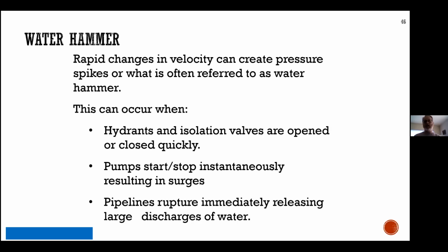And if you've seen pressure gauge readings on a system where someone has shut a valve closed, it can be up to 200% of the operating pressure in the system. Well, that will damage pipeline.